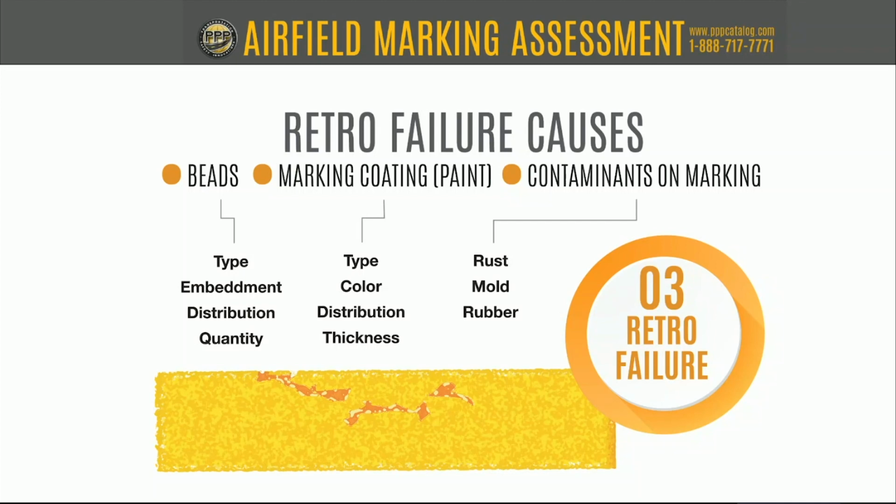And these tips are designed to feather the edges. They're architectural, so they're really designed to spray, let's just say, a vertical wall or something. So you spray across and it overlaps and the edges overlap back and forth, so you don't have these runs.